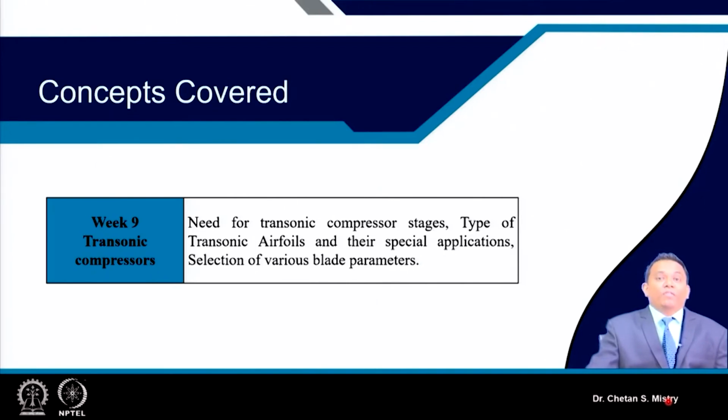Initially we felt that a sharp edge gave benefit in the sense of anchoring our shock. But it works worst under off design condition. Off design may be a change of speed or change of mass flow rate and those parameters. It may be possible that the flow will go subsonic in that case.